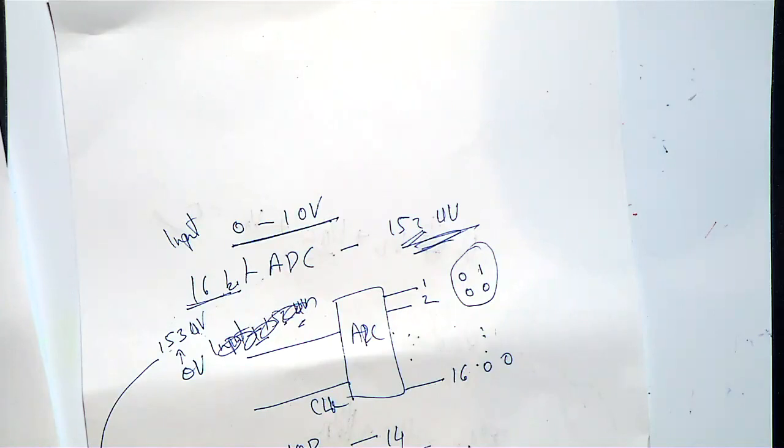I think I told you previously. I used a 16-bit ADC in the past, and when I connected it, the output was jumping. LSBs were jumping, so I didn't get the 2 raised to 16 minus 1 resolution, and couldn't calculate the voltage because of the effective number of bits. Then I checked the data sheet and saw the effective number of bits they had given was 14.5.